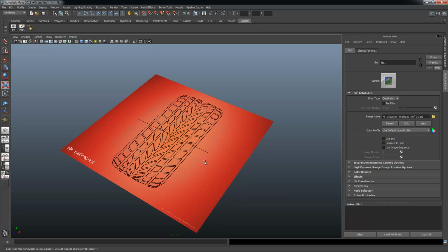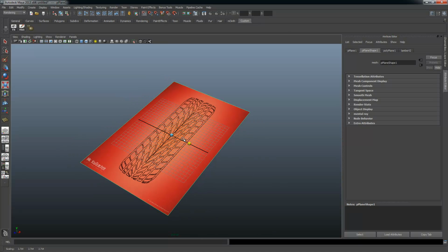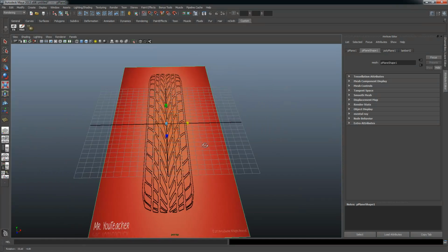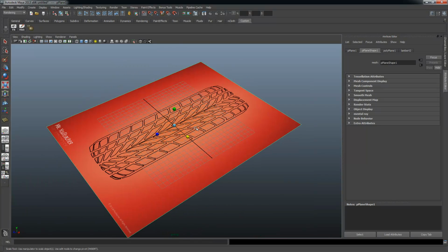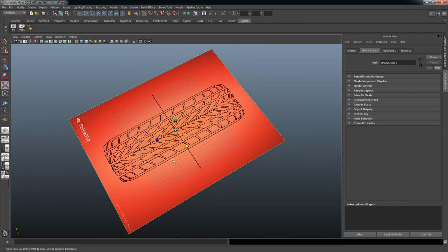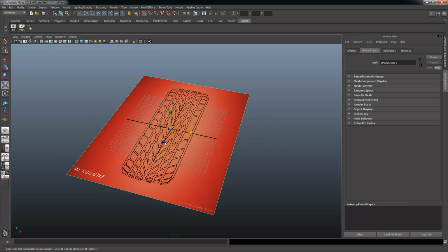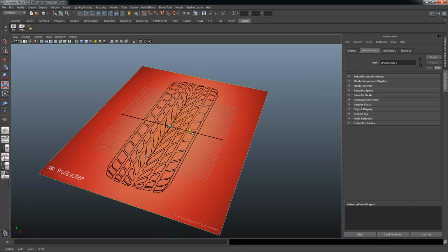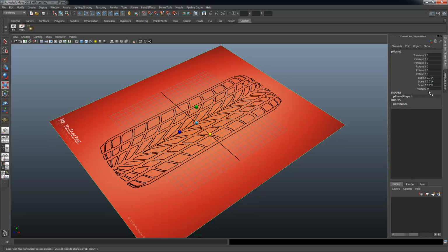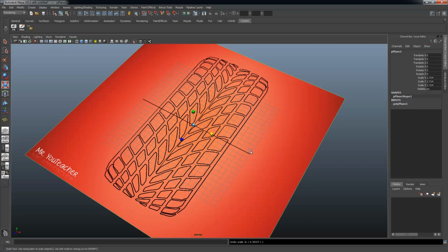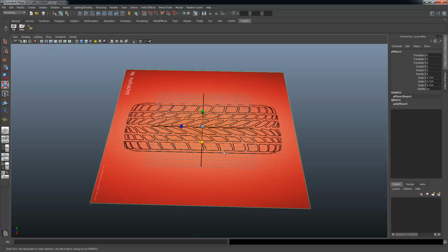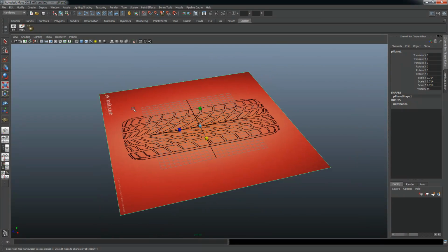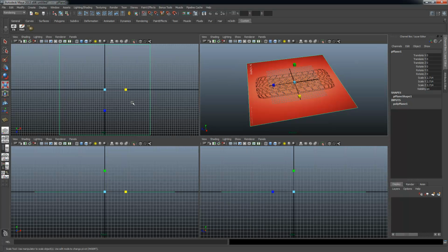What I mean by undistorted is that the aspect ratio of the image is actually the same as the one I created in Photoshop. If you create your reference plane non-square, and your image non-square, what will often happen is your image will get squashed, or your plane is squashed and it'll squash your image. It's very subtle. You can have even a 20% squash on this, and that will throw your entire model off. So what we like to do is always make this 100% square, and then everything's going to be copacetic and we're never going to get anything squashed and distorted.